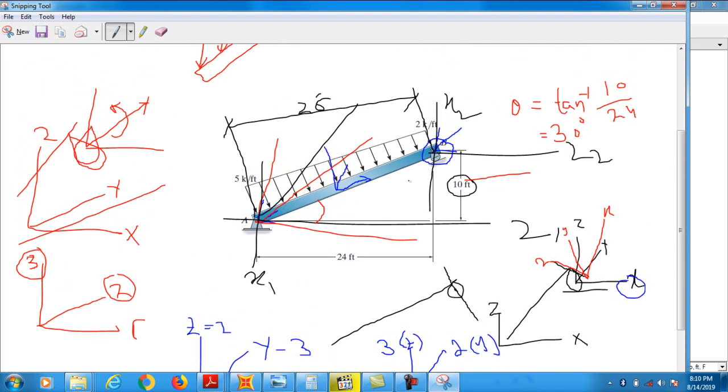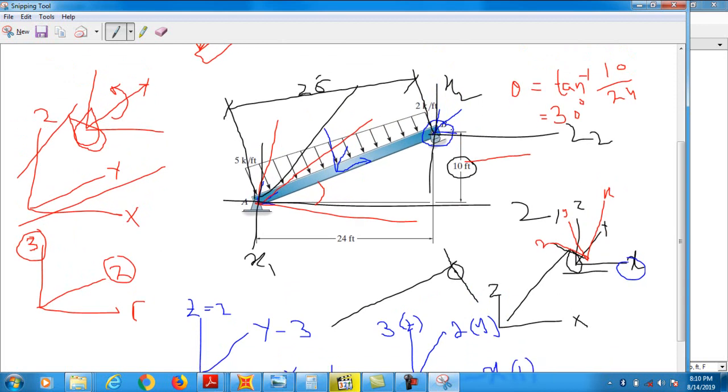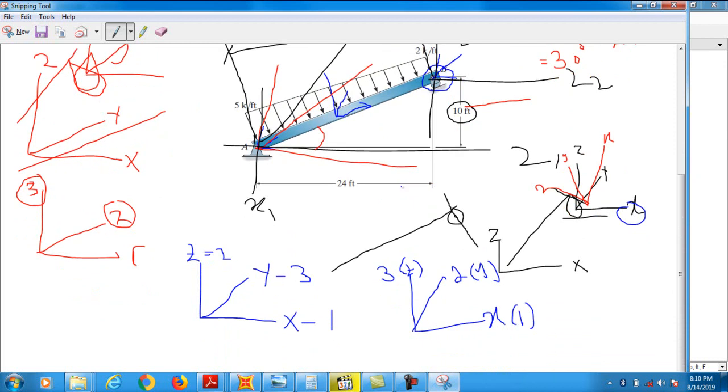And in rotation, you must know about which axis I am rotating my joint or my element. Clear? When I insert an angle in degrees, so that SAP2000 rotates the element, it starts the degree from z.